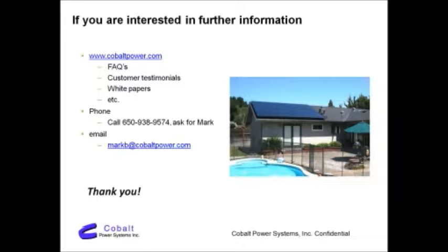In terms of tilt angle, it's really not very critical. There's something called orientation slope factor, which is a number between 0 and 1, and it takes into account the azimuth, which is the direction facing, and the tilt angle. South facing 7 and 12 here in the Bay Area is 1.0, so that's the best you can get. But south facing 4 and 12, you builders know that's an 18.4 degree slope. That's 0.97. So a 4 and 12 roof is only 3% lower than a 7 and 12 roof.